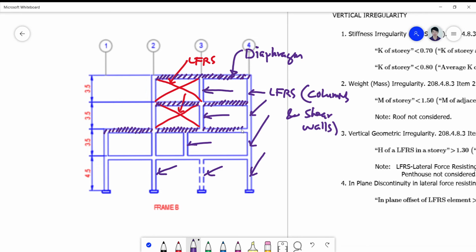Sometimes a portion of your lateral brace can be helping, no, the action of the diaphragm to transfer the loads from one column to the other, but basically the main purpose of a cross bracing is to add to the strength of your LFRS system. So mainly the diaphragm is made by slabs and beams.